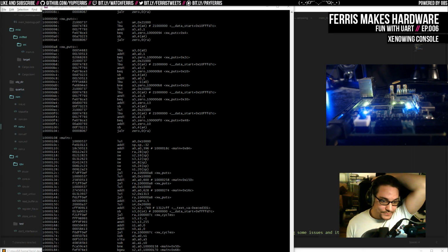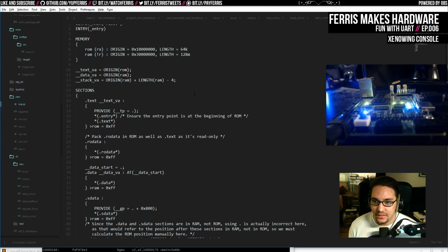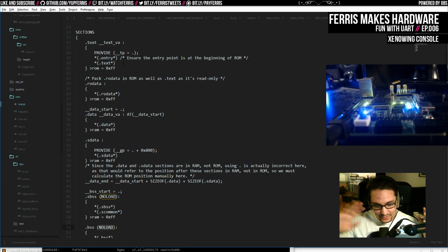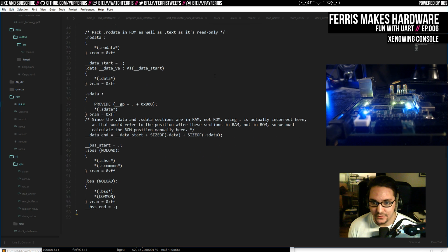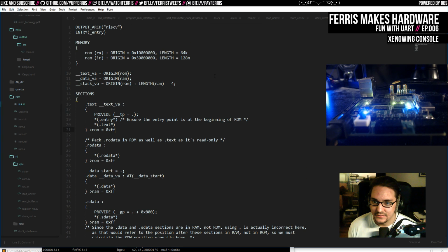Oh, that's cool, Miss Visser. Both that you're working on Pipeline Core and that you borrowed that linker script. I think in this one too, it's missing a bunch of sections. I think GCC can output a ton of different sections, but I just did the ones that I've seen so far and the ones that I know where they're going to go. And if this causes problems, I don't really care. I'm not going to implement libc, and I'm only going to take this so far. So whatever works is the best thing.